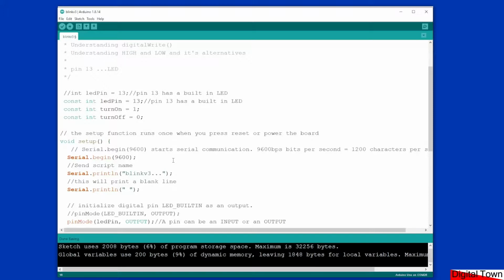at the moment that I've been writing that controls various displays and electric motors and different sensors and different things. And so what I've done is, instead of keep using high and low, I actually use a value of turn on and turn off. And the reason I've had to do that is, in my code I've got one item that when the pin goes high it's turned on.